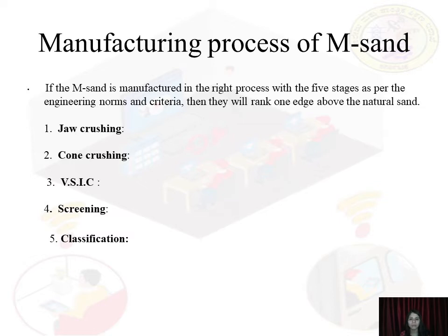That means the crushers are used to crush the stone, and then screens are used to screen out the small sized particles to get the required size of grains and sand. It is noted that the dust from the crushers has to be removed, which is not good quality and does not lead to good quality manufactured sand.